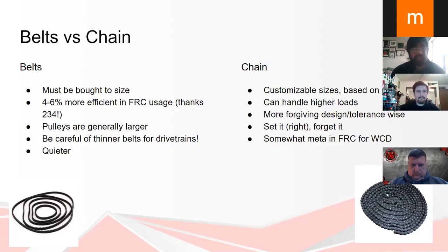The big thing with belts and drivetrains is they'll work, they're fine, but you really need to be smart with the size of belt you use. I've seen and have heard lots of issues with improperly chosen belts, because if they're too thin or the pitch isn't that great, I've heard of teams shredding the teeth or snapping a belt, and that means now you've got problems moving.